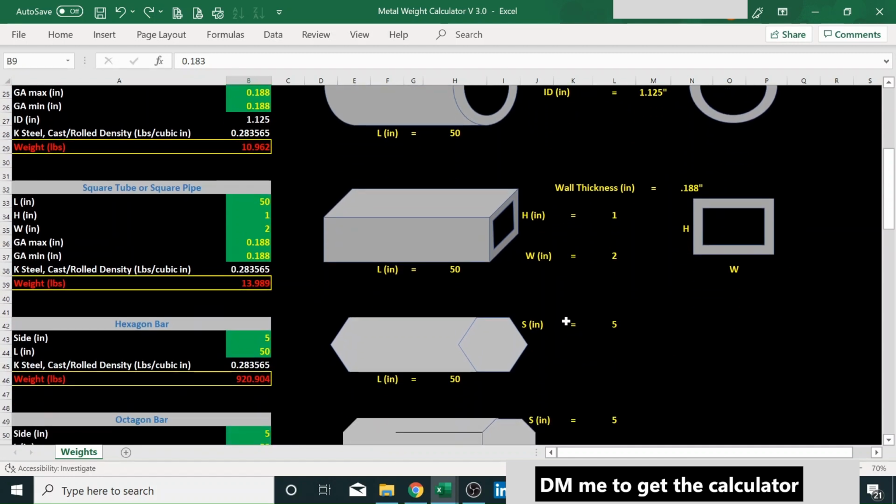We do a similar thing here for this rectangle. In this case, it's rectangular. It could be square if we put 1 inch as one of the sides. But let's say it's a rectangle here. So what we do is we get basically the bar volume with those outside dimensions, and then the inside dimensions would be whatever our height is, which in this case is 1 inch, minus 2 times the gauge.